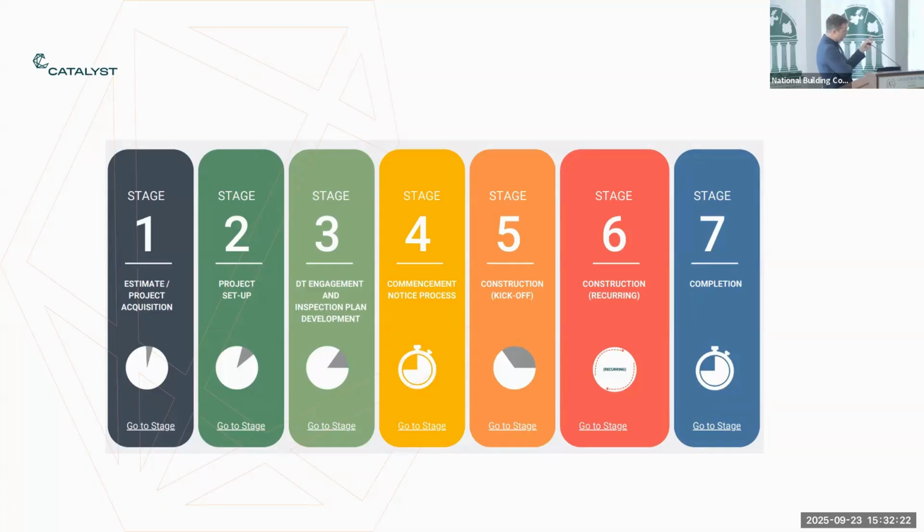And then in the wording as well, although we'll take a first draft, we'll generally have some input into how that project is going to be worded on the BCMS. It is important as best you can to put in information like grey box, white box, or shell and core, or Cat A or Cat B fit out now at commencement stage, so that when you get to the completion stage and you're handing over a shell and core or a grey box, there isn't, I suppose, a misunderstanding from a building control perspective, expecting that you were going to hand over a finished product. What you're actually handing over is a shell and core or kind of a white box finish. So getting that into the wording of the commencement notice early on is very important.